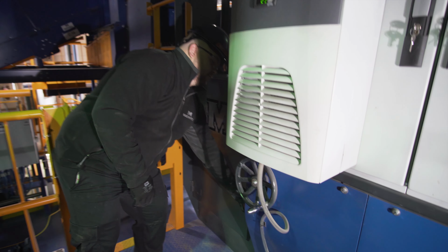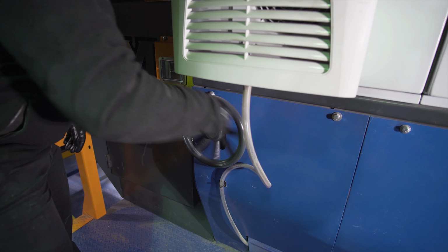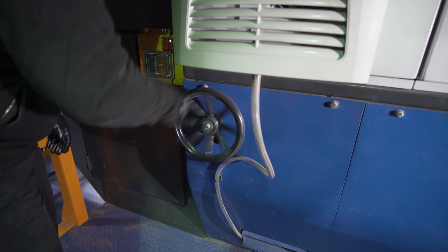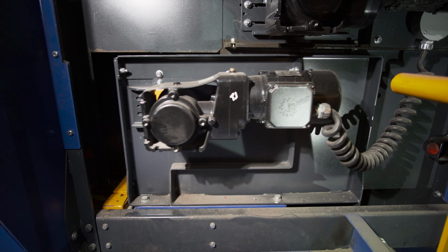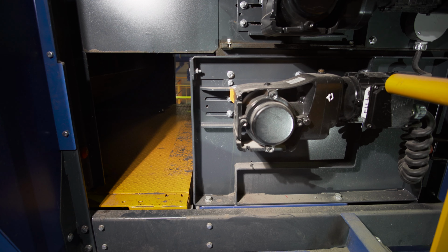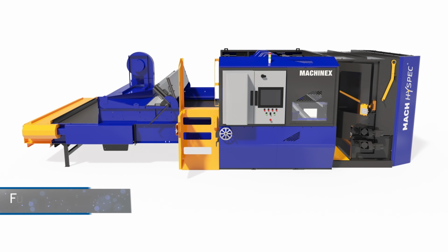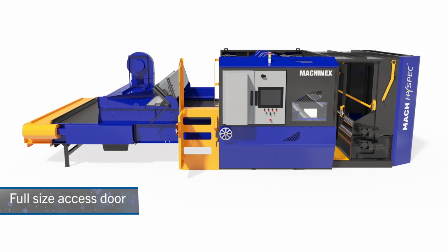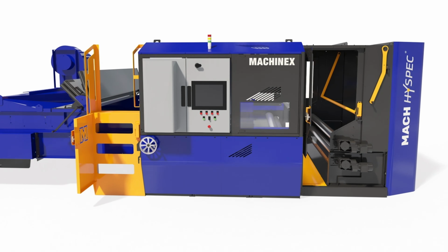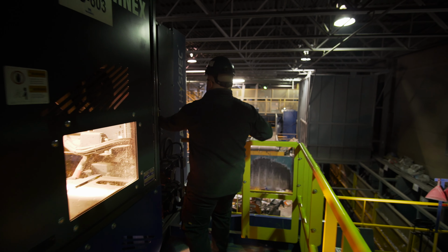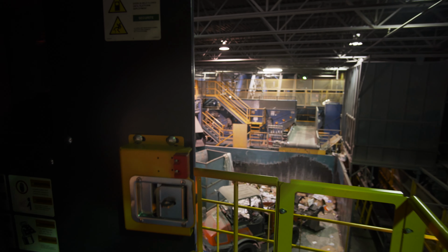Okay, so let's have a look on site at the latest features of the redesigned ejection hood. The first thing that the technician has to do is to turn the round handle to move the mobile platform to its final position inside the ejection hood. Once this is done, the technician has to rotate the yellow handle, which activates the internal guardrail system. The purpose of this internal guardrail system is to protect the technician from falling inside the ejection hood, but it's also used as a fail-safe system to prevent the technician from opening the door without having the guard in place.